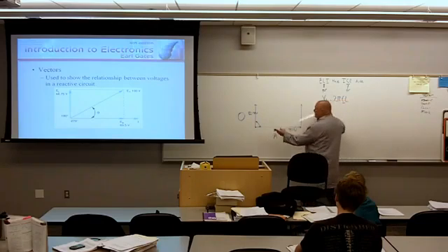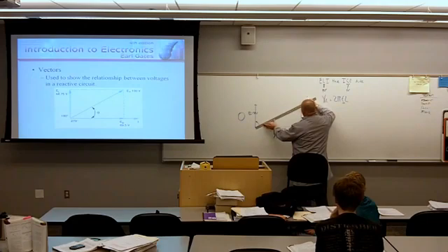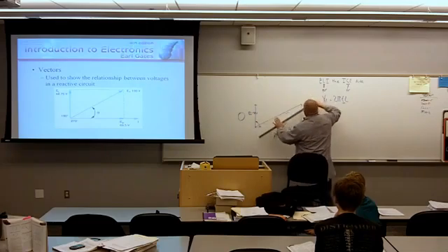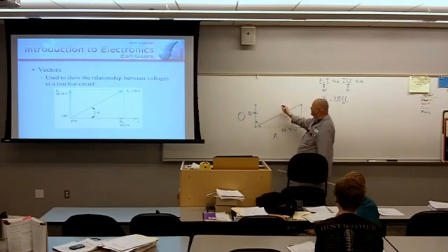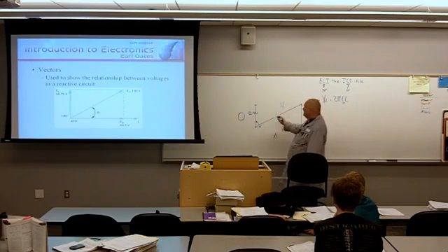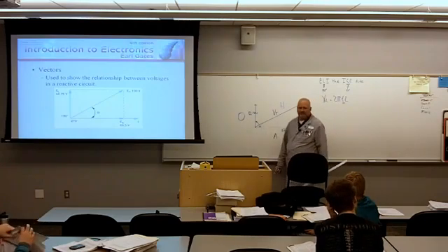And then I'm actually going to draw a line from my reference to complete this right triangle. This line that I'm drawing here is going to be my hypotenuse. And the combination of the voltage across my resistor and the voltage across my inductor is going to be my voltage total, or my hypotenuse.